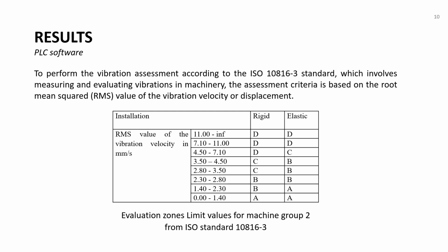These zones, as you see in the table, serve as a guideline based on the machine condition. The limits described by the standard are only intended as a general guideline, and in some cases they cannot be applicable to certain machinery, just like in our case. The worst case classification is usually determined by comparing the two possible outcomes from velocity and displacement. After that, the classification results are published to the MQTT broker for the VR application.